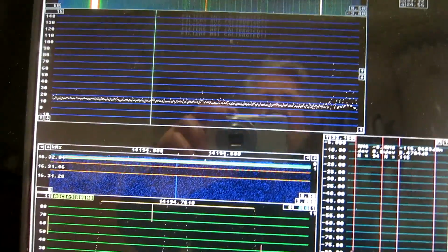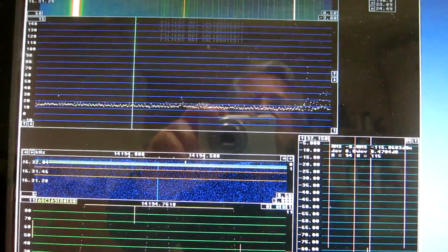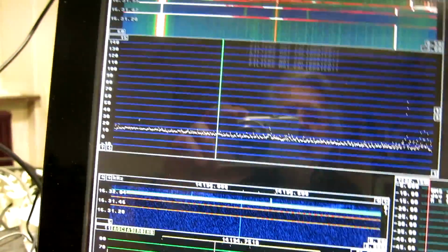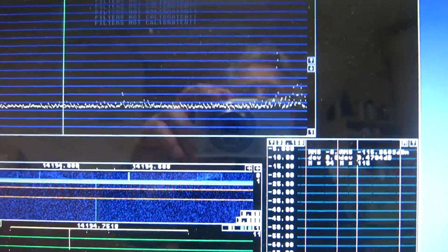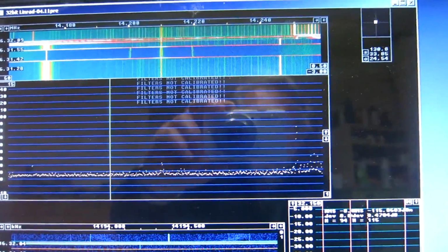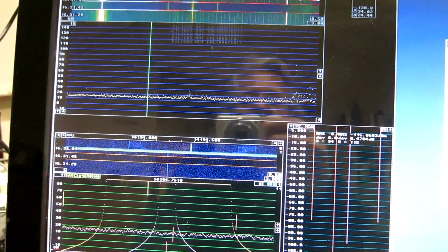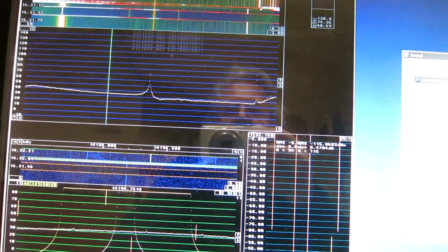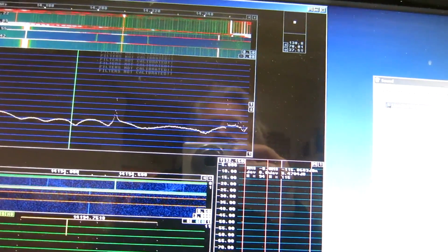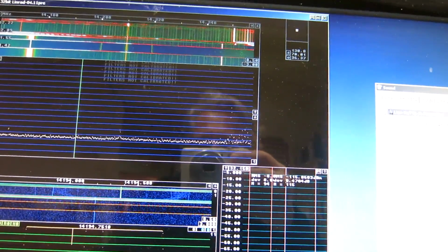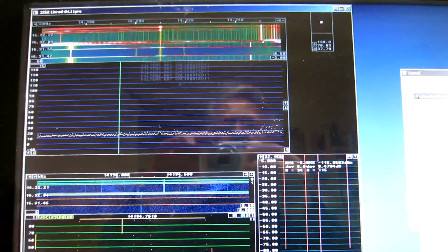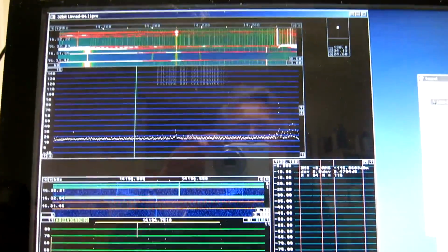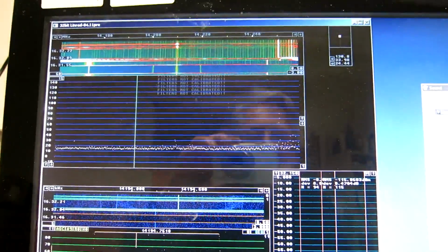And here things start to look not so pleasant anymore. There are many little spurs and several not so small spurs. It seems I have to reduce the signal level. I back off by 1 dB, 2 dB, 3 dB. So it's not a saturation problem, it is a problem with poor digital filtering in the sound card.